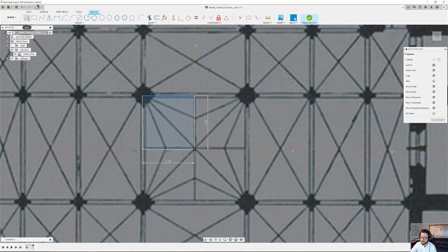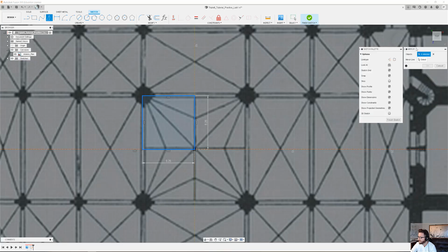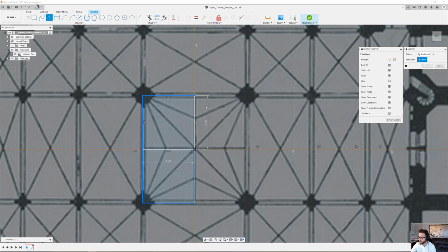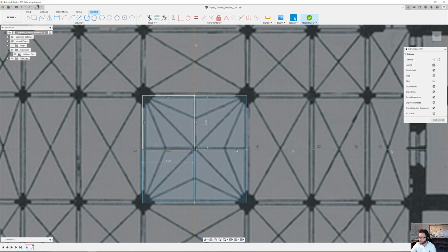I'm going to do it sort of the easy way, which is I'm going to double click on the entire edge, and I'm going to use the mirror tool, and that opens up the mirror over here. And I'm just going to select a mirror line, so I'm going to say all 4 of these sides get mirrored from here, and I'll hit OK. Alright, pretty easy. I can do that again like this, and then say mirror, and now I want to mirror on the vertical, and I'll hit OK. Okay, so that's pretty easy, not too bad.